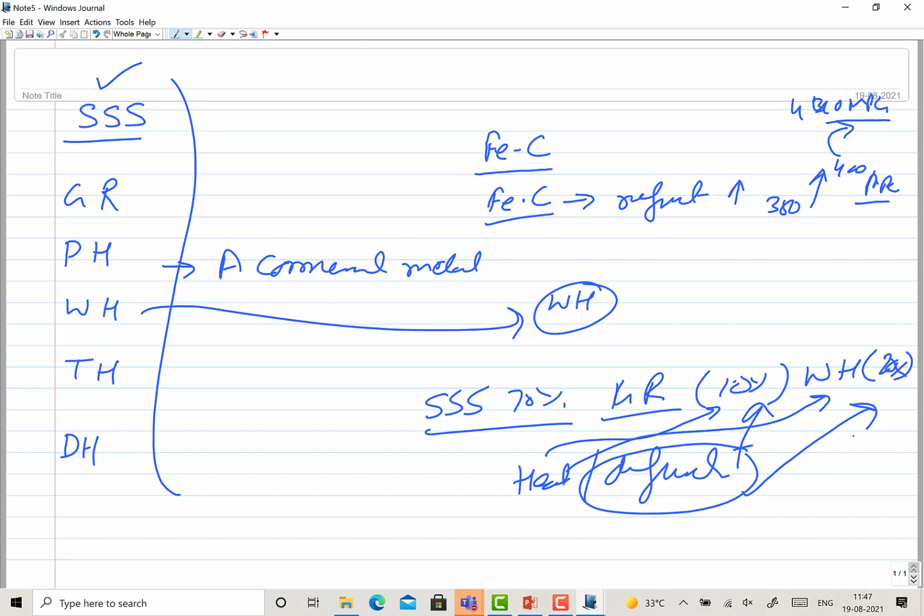So it is the relative importance of these two process linked factors, that is heat and the deformation. If the heat is dominating or if the deformation is dominating, accordingly it will determine if the grain refinement effect will be lost or it will be gained, or if the work hardening effect will be lost or it will be gained. So these are the things of analysis.